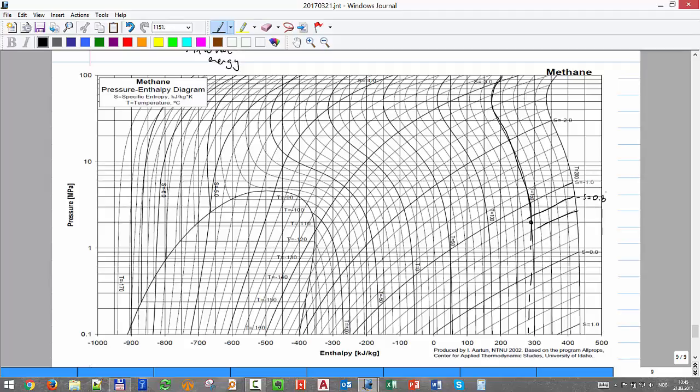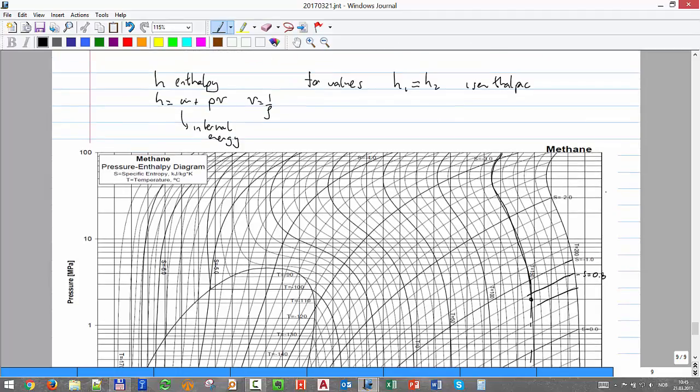So for example, some of you were asking, for this Snøhvit case, what delta P did you get across the choke the first year, if you remember? I think the temperature of the reservoir we said was something like 90 Celsius, so we can assume that's T1, right? Delta P, I think you had values like 160, 70 bar, was it?